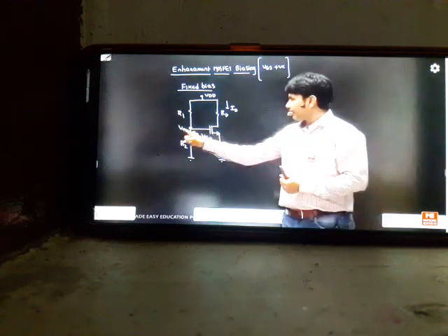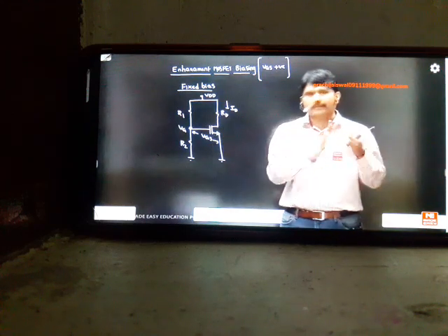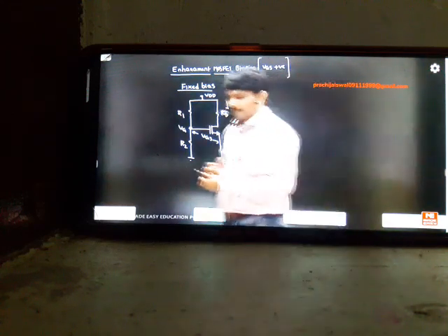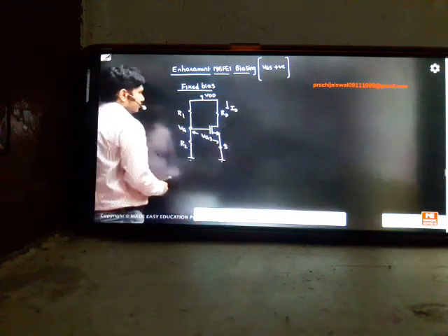Why, sir? The gate voltage becomes VGS directly. If the gate voltage becomes VGS, you have fixed your operating voltage as VG. That is called fixed biasing. So this is the trick called fixed bias circuit in the first lecture. Let us complete this. There is no RS here, so it is not a voltage divider bias technique.